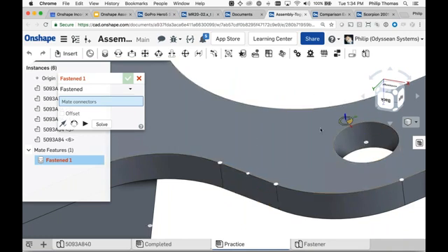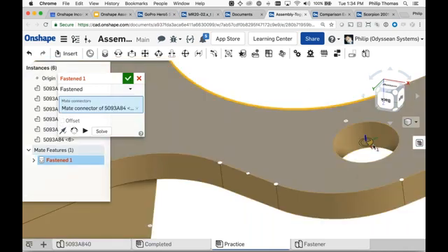Here is a face that contains a circle, therefore there is a center here. This is actually the center of this edge, this fillet on here. And the cylindrical face actually has three mate connector points. One at the end of the cylindrical face, one in the middle, which is very useful because it's always in the middle, and one at the end.